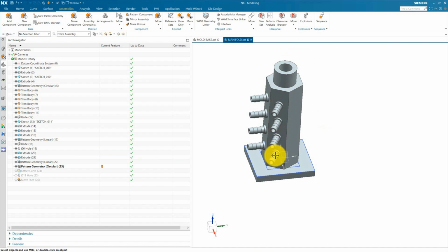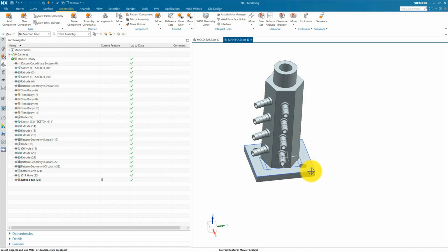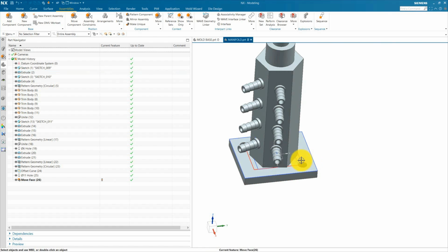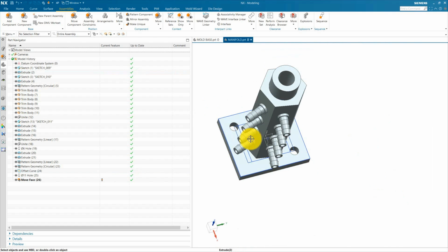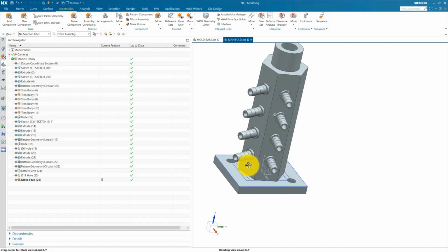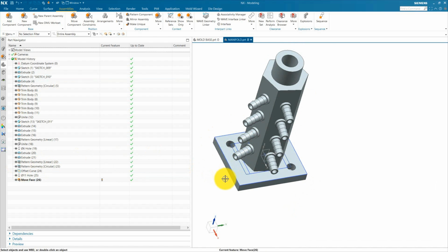So for example, this manifold is used for in, so in the cooling system the in pipe is going to be installed in one of these nipples. This manifold is assembled on our housing and going to be bolted with this. We can also provide a 4-hole if the manifold is large and heavy according to your design. This is not a fixed design. You can change this according to your requirement.